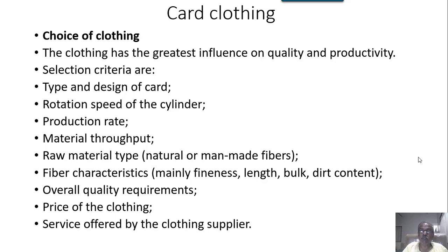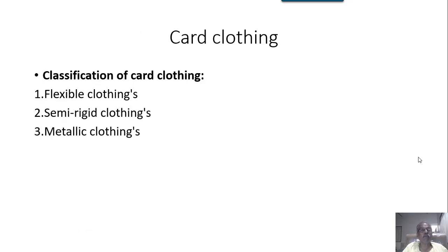As I have stated in the previous session also, in case of the modern card, like Rieter's card, C81 or something, we are having continuous grinding, the licker-in and top online, continuous grinding for the cylinder and continuous grinding for the flats. So like that we have the changes.